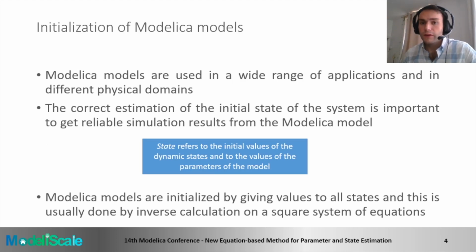So, initialization of Modelica models is, of course, extremely important as for every model, because it is necessary to correctly initialize a model in order to get accurate predictions by the model. So this is why it's very important for us to correctly initialize the model. And by initialization, we mean finding an accurate initial state for the model. By state we refer to the initial value of the dynamic states and as well to the values of